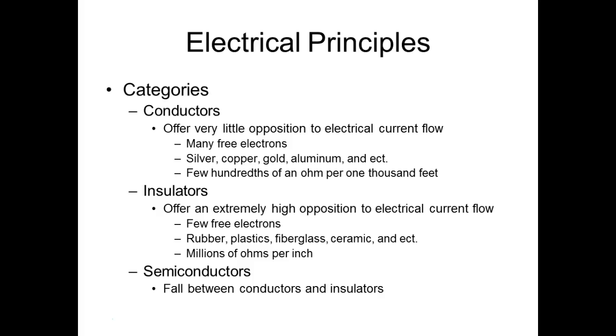So anything, usually copper, if we're going to expose copper to the atmosphere and we're concerned about that, we'll coat it with gold. Tin's becoming a very popular coating for things that have a short lifespan. Tin will oxidize, but it's got a real high oxidation level, so it takes longer. Originally in computers, they used to gold plate everything. All your connectors were gold plated. Now you'll see a lot of tin plating inside computers because computers have a limited lifespan before you get rid of them.